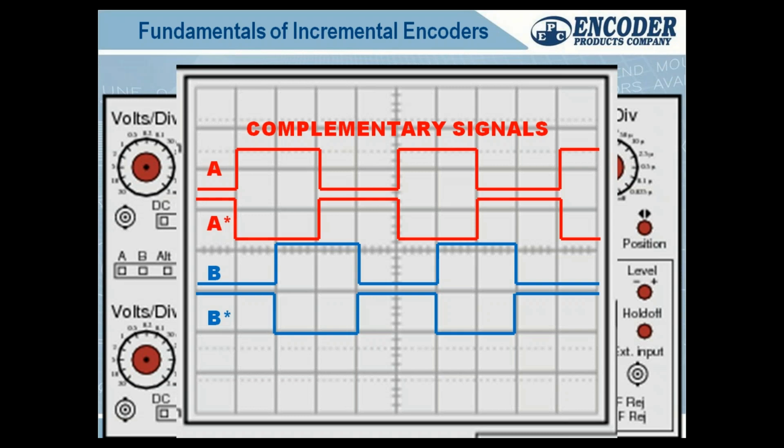It is exceedingly rare. I've only seen it a few times, and it's usually caused by overvoltage, that the ICs go bad. So if you have random counts, high or low, it's probably noise, or a bad connection. More often than not, it's noise. Encoders do not like noise. We do get into that today, how to mitigate noise. In fact, that's what this next section talks about as well. And then one more question.